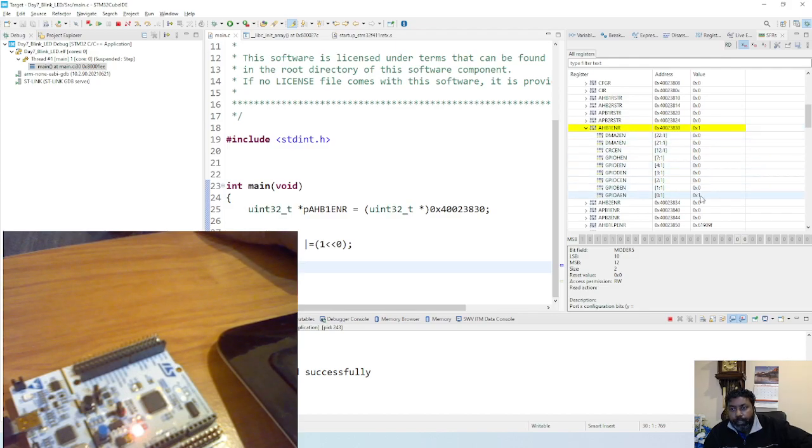So this is the code that you asked the microcontroller to do. Before I did it manually, but now you have written these 2 lines and you executed by going into step into, and by default automatically you told the microcontroller you enable the peripheral and also you set up the GPIO enable, port A enabled. So what is the next step? Next step is to set the mode register. How are you going to do that?